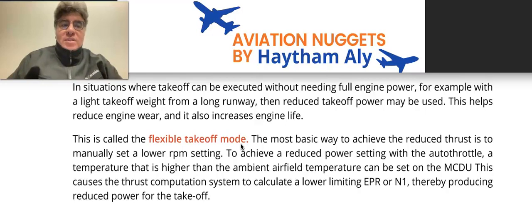Why does the pilot do that? To increase the life of the engine, to reduce engine wear. Okay, everybody? To reduce the exhaust gas temperature, EGT, on the turbine, so the turbine can live longer.